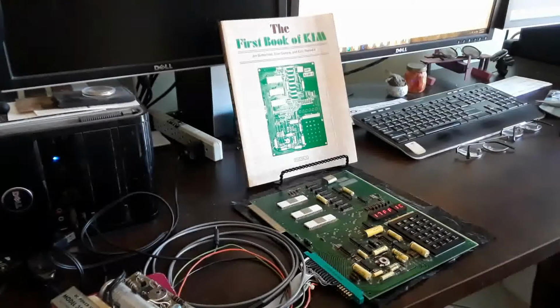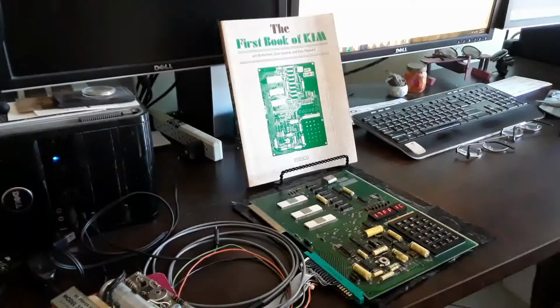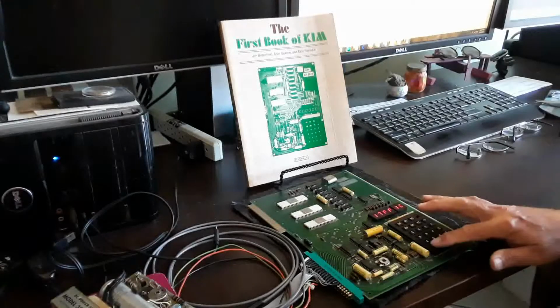This program is a very simple program that will exchange the data from two different memory locations, specifically memory locations 0010 and 0011. So let's go ahead and start by looking at these two memory locations and entering our own data values into those locations. Okay, let's start by pressing AD again and going back into address mode and selecting address 0010.